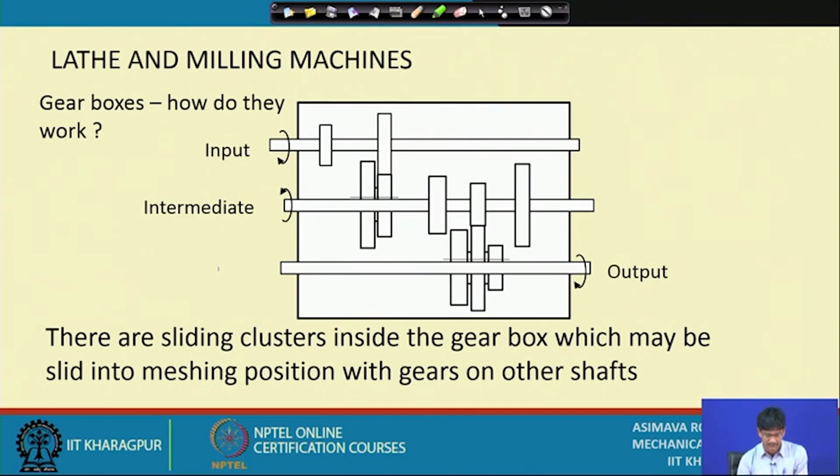There are mainly 2 gearboxes on the lathe. One is the speed gearbox, that means speed changing, and another is the feed gearbox or feed changing, and basically they use some device like this or some other related devices like the Norton tumbler arrangement, meander drive, etc. When we get time, we will definitely go through these.